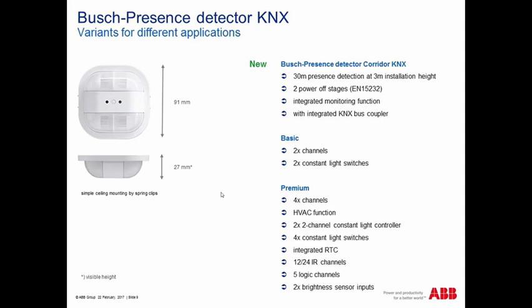And one difference here is that in the other presence detectors, we have so-called sectors, sector 1, sector 2, sector 3, and 4. And these 4 sectors can be activated or deactivated independently and separately. Here is the difference. In this one, both sectors here and both sectors here are initially grouped, and you cannot change it. That means a combination between sector 1, sector 2, sector 3, and sector 4. So this is the only difference here.